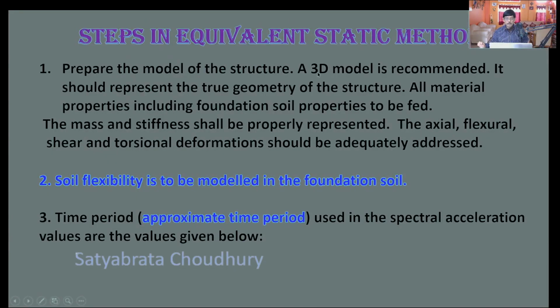Now, what are the steps to be followed in the equivalent static method of analysis? These are the steps. Prepare the model of the structure. A 3D model is recommended. It should represent the true geometry of the structure, and all material properties, including foundation soil properties, are to be fed in the model. The mass and stiffness shall be properly represented.